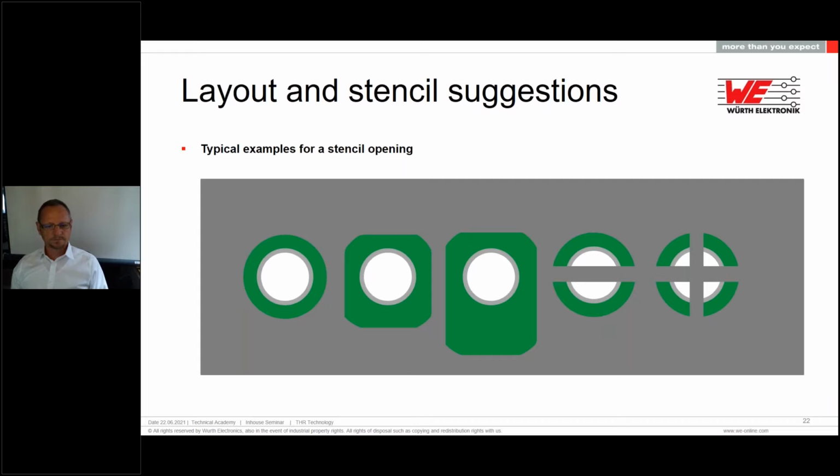And so we have the corners also rounded, so that the lift of the stencil will not draw any of the paste with it. Yeah. So number 3 is used when more solder paste is required, like the overprinting I was talking about. And also here the edges are round.